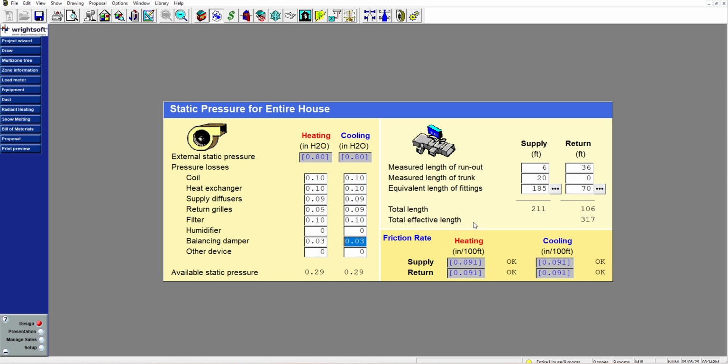There's a pressure loss that occurs as the air is flowing. That's because there's friction between the flowing air and the walls of the duct. Again, think about a straw, right? If you're blowing through a short straw, no resistance. Make that straw longer, and at some point you're going to start to feel that resistance. You're going to have to push harder. So same thing with these ducts.